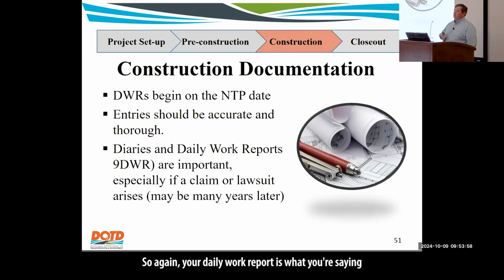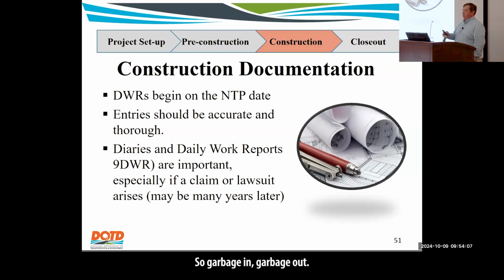Make sure they're thorough. So again, your daily work report is what you're saying went on the job for that day. So garbage in, garbage out. If you're not providing much information and there ends up being a claim or an issue later on and we've got to go back and look at those and there's not enough detailed information, he who has the most documentation wins. And it might be that the contractor had more documentation. No, I had all these pieces of equipment out there, I had these people out there, all that sort of stuff. So make sure we're documenting everything properly and that it's project specific.